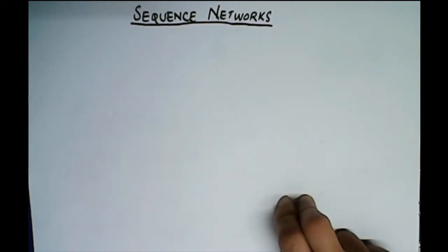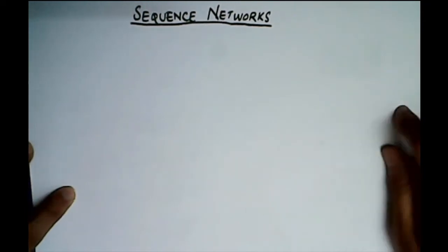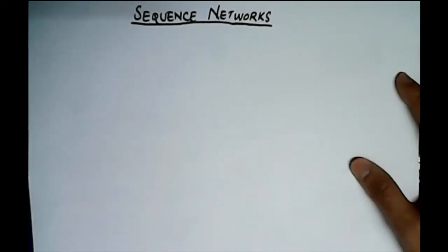However, the positive and negative sequence current will still be flowing because it doesn't need a fourth conductor to flow, right? So it is recommended to draw the network in terms of positive, negative and zero sequence. Whichever current is not flowing, we can mark it as open circuit, right?